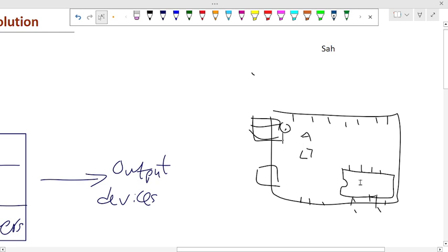So the microprocessor has input and output pins. We said that before. And how do you make use of these input and output pins in a microprocessor? These pins are connected to these other pins we have in the Arduino. So it's like the Arduino serves as the extension of the microprocessor, so that we can interact with the microprocessor.